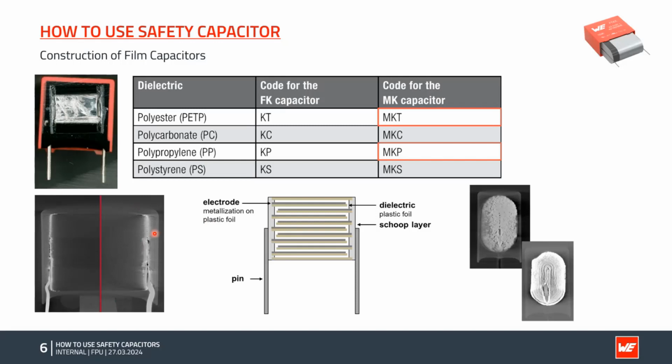On the left side here, a comparison between a good connection to the winding, and here a not so good connection to the winding, because here it's really pressed inside the winding, which means it could cause short circuits. So such things could be seen in a computer tomography way. And on the right side, this is the choke layer. Actually these small balls, maybe you interpret it in a different way, but for me it's like small balls.